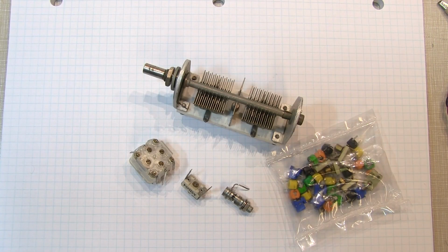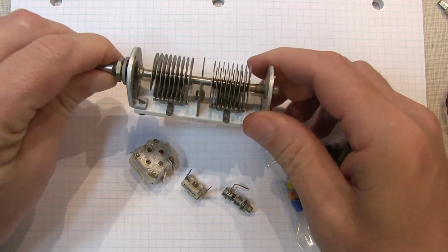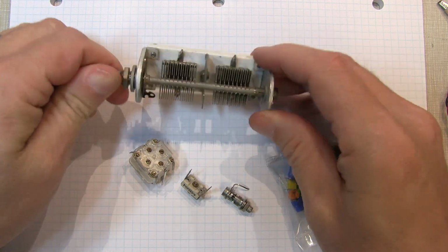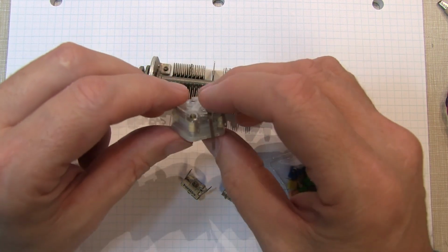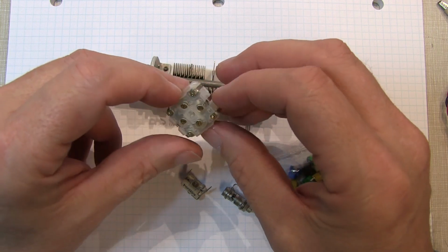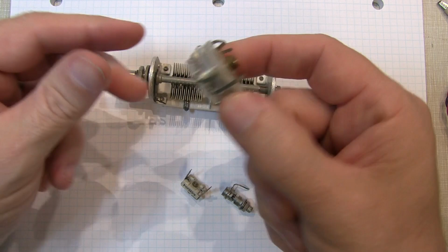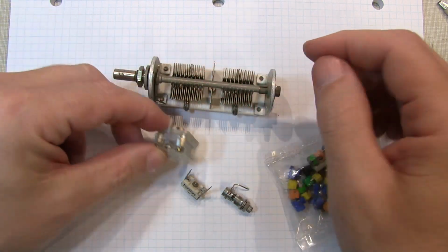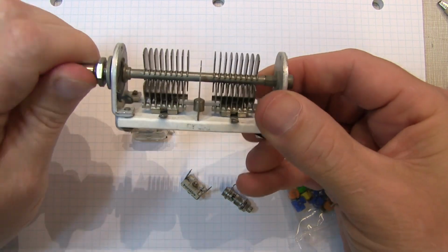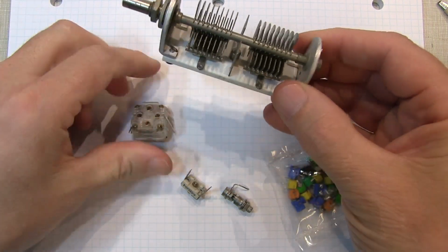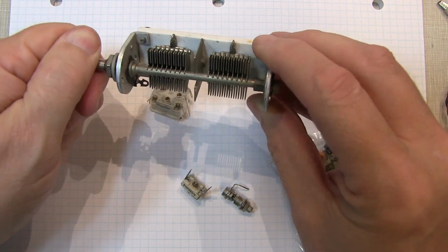Now, of course, there are lots of varieties of variable capacitors as well. Some of these larger air dielectric kind of bread slicer variable caps, and the smaller what we call polyvaricons, because they are like a polyfilm variable capacitor. Typically, they've got some trimmers as well as kind of main tuning on them. You find these in some of the older transistor radios. You might find some of these in some of the older larger transistor radios, or tabletop or even tube radios and things like that, to make the tuned local oscillators for tuning the radio around.